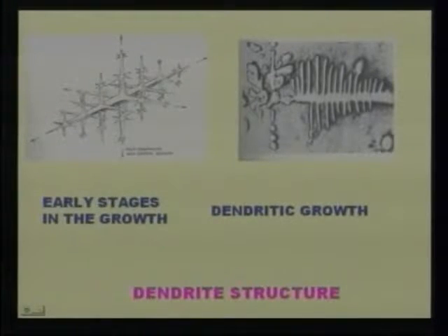Now you can see a real metallic picture of the iron carbon material. You can see this is the backbone of the dendrite growth. First it will form this backbone, then these are slowly absorbed by cooling. When cooling continuously takes place, slowly these stems are absorbing the smaller crystals, and the entire liquid metal solidifies and you will have a growth. This type of growth is called dendritic growth.